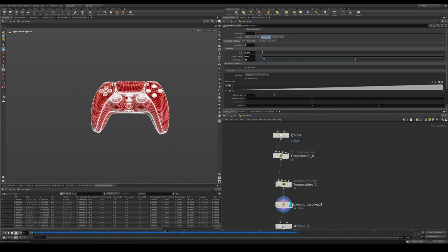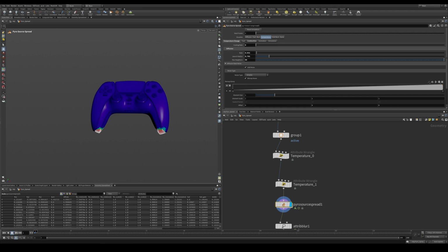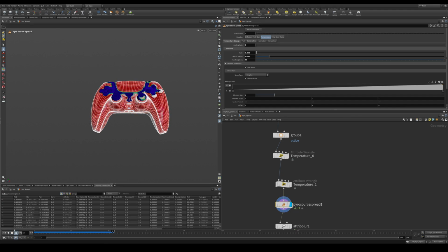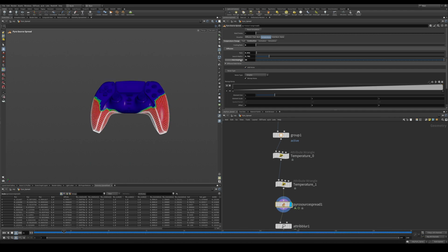So that was pretty quick. We can do the rate maybe slower. You can see that this section here was not selected, so we probably need more points here. We could put 60. We'll reset it because it's a simulation. And now it's being taken over. There's also max neighbors, which is the amount of points that it's going to search. So the more points here, the more it samples the spread of the search for the diffusion.